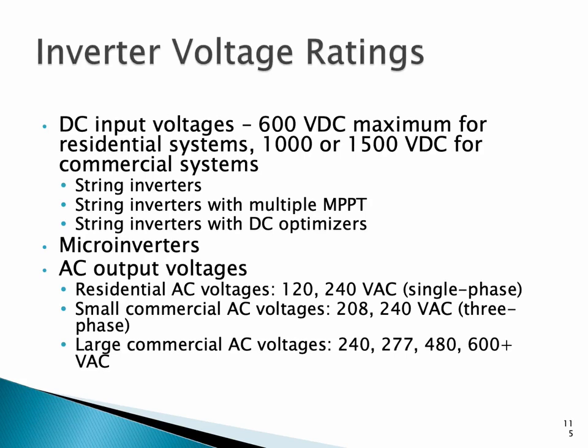Microinverters, they're going to invert from low voltage DC into 240 volt AC right at the module. And so it's going to be running at 1 amp or thereabouts, maximum current, 240 volts, and then that microinverter just plugs into a cable, and there's roughly about 16 or so modules that are possible to make up a string, all connected together to make a total of 20 amps output. So that's the building blocks.